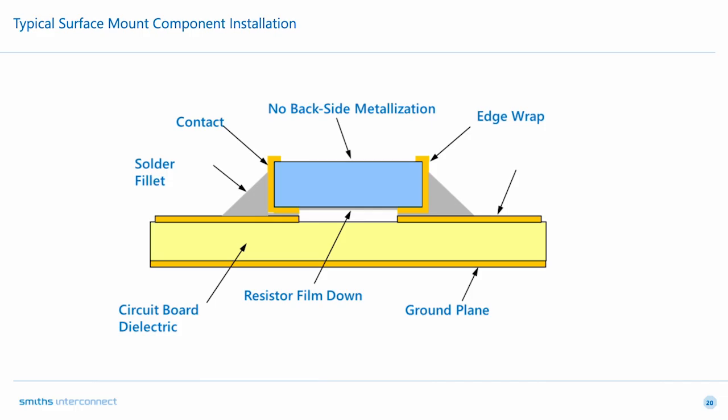From the ThermoPad selector tool, I'll just randomly select a component. And this is from our WTVA family, a 3dB -7. From there, we get our visual of our ThermoPad response and what the amplifier response is going to look like after the ThermoPad is used to compensate for the temperature change in the amplifier. There's a quick reference to the specifications with also pictures of the components as well.